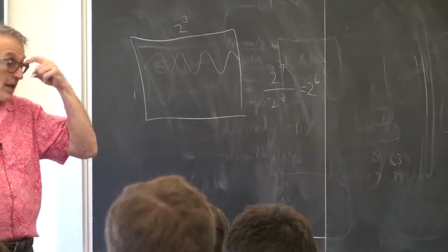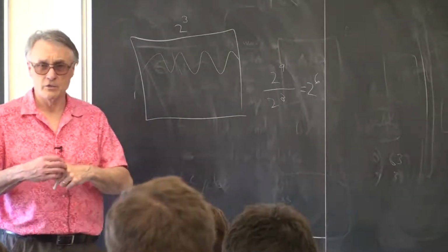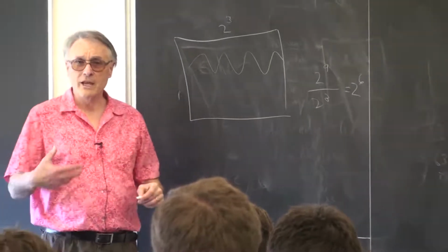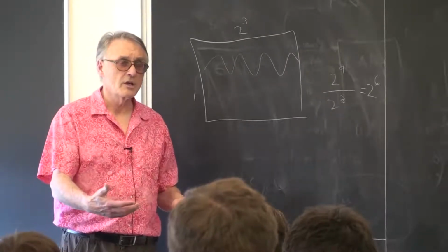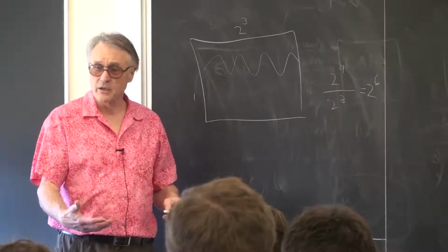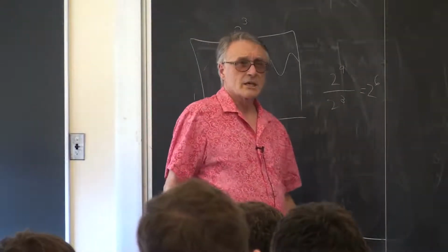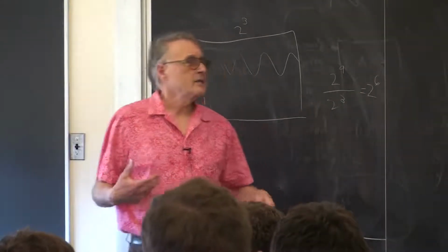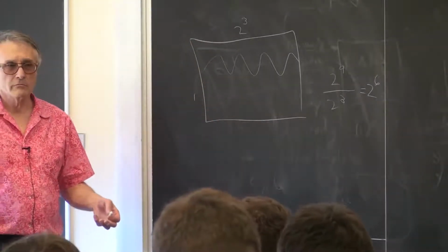Right, so now we say, how many points per radian should we have? Because the natural frequency units for the solver is radians per second, not cycles. So you divide that by 6, and you get something like 10 points per radian, or something of the sort.